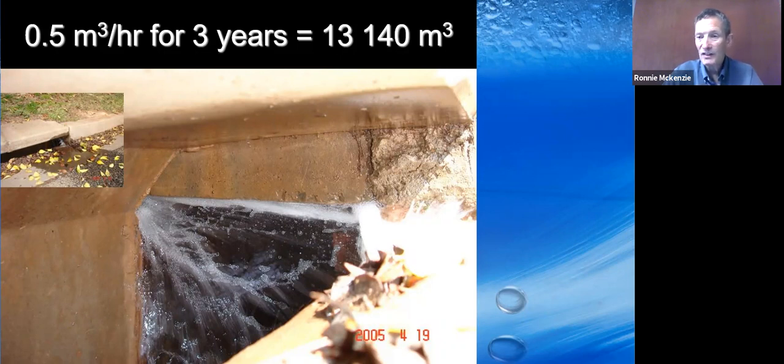So just one of the takeaway points when it comes to water utilities, you should be fixing all reported leaks within a day or a maximum of 2 days. Unfortunately, most of the municipalities we work for, that repair time is generally in a matter of weeks, if not months. And that means that we're losing a lot of water, particularly through the smaller reported leaks.